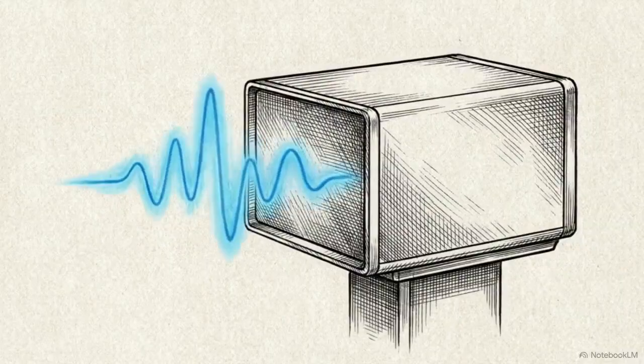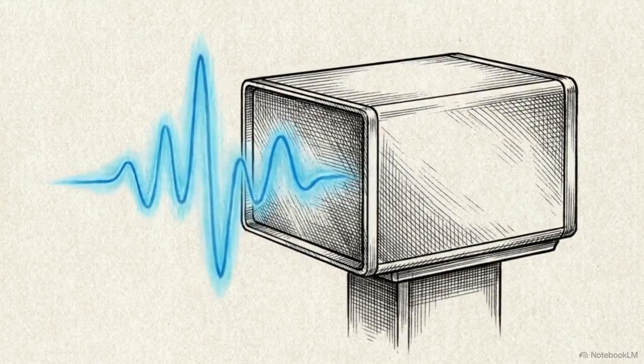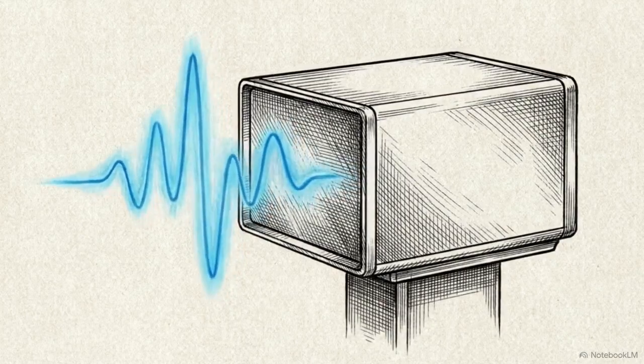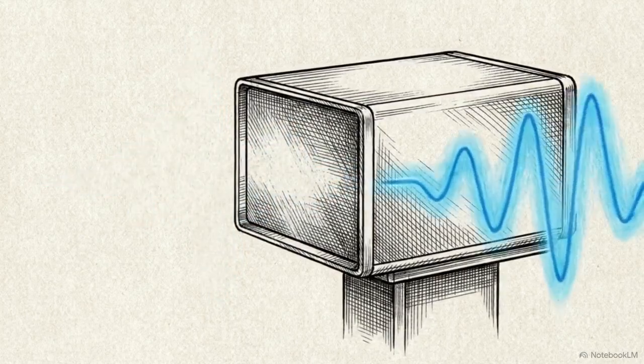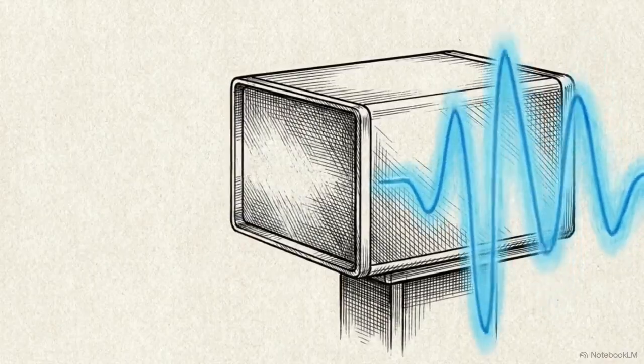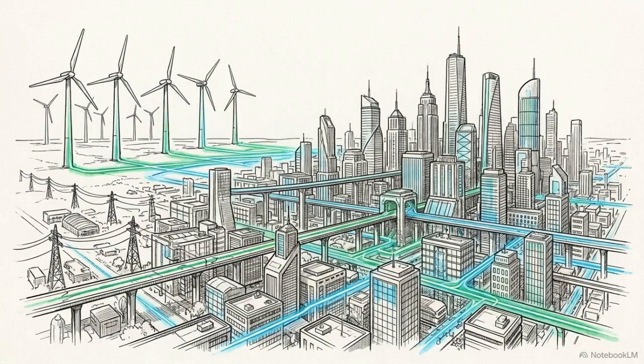The design achieves highly efficient bidirectional AC to DC power transfer without relying on a massive, failure-prone DC link capacitor. Synchronizing this high-frequency link topology with deterministic embedded control provides the density and efficiency needed for direct AC grid integration.